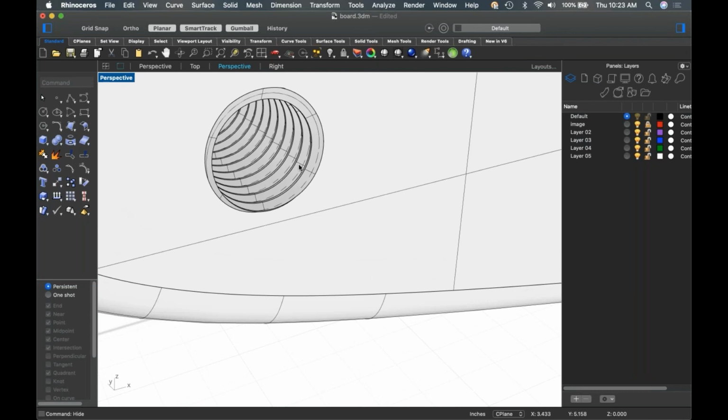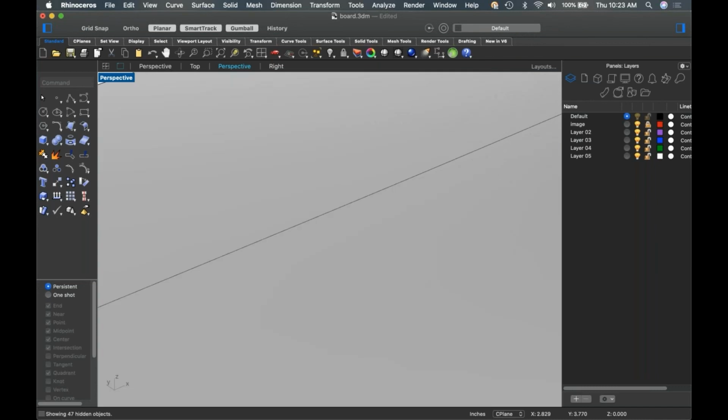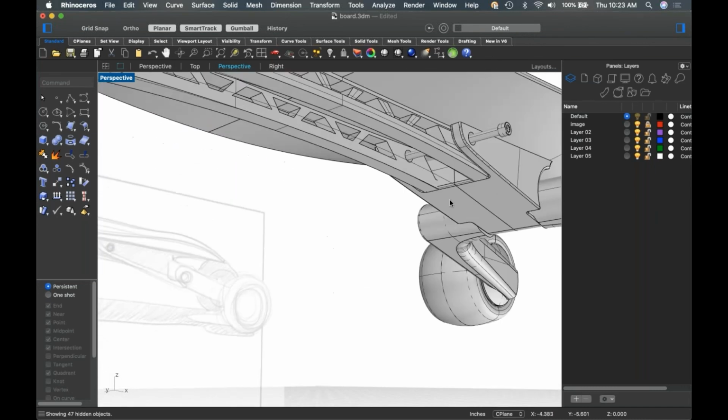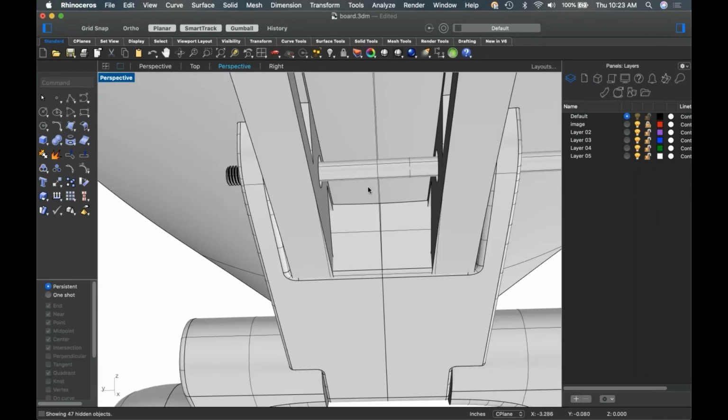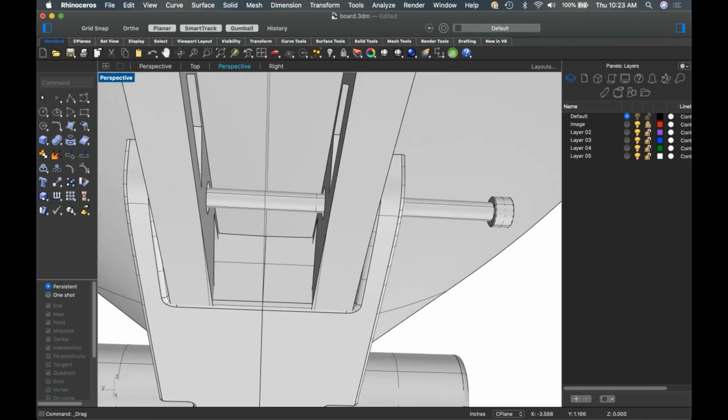And if you print this, and as long as your scales are correct and you didn't mess with the bolt when you just brought it in and used it, these threads, if you just run the correct size tap through it, will clean up perfectly, and you'll be able to screw it in by hand. So people are always like, well, there's bolt gen and all this other stuff for doing bolts, and I'm like, yeah, I don't do that.